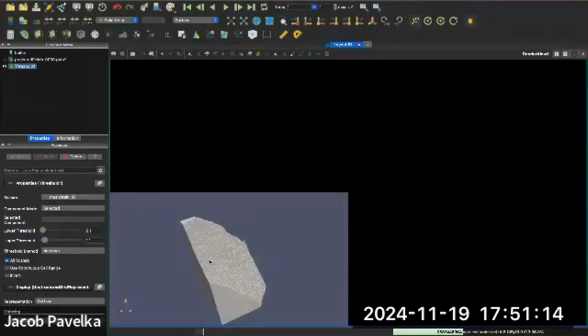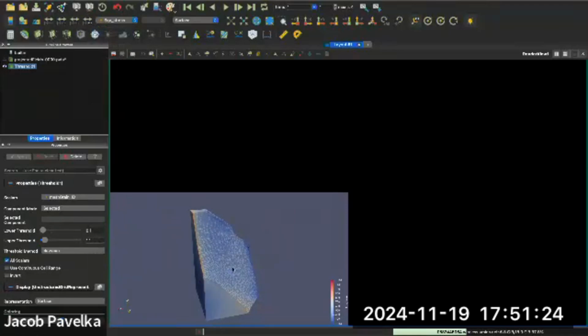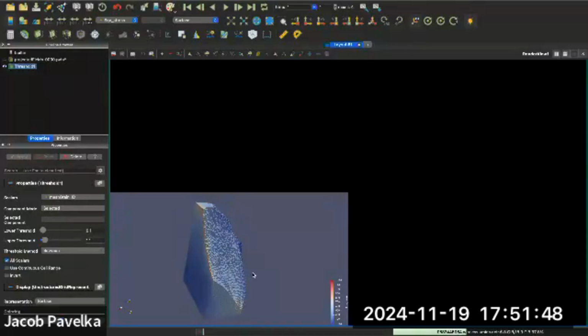Okay, so here I'll look at just one grain, the big grain. And now we can see sort of inside the material. And at this point where all three of those grains are meeting, there's a high stress concentration. And so from this, we have sort of validated that those things that we saw in the experiment emanating from this grain triple junction, it is due to some stress concentration there. I'll show you guys one more thing.